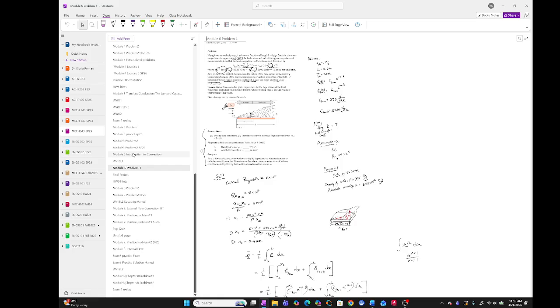Now, for intro to convection and external flow, I did go through the equation manual here in class. Everybody remember that? Boundary layer thickness, thermal boundary layer thickness, hydrodynamic boundary layer thickness, the Nusselt number. The Nusselt number, Prandtl number, Reynolds number relationship, for different conditions like constant surface temperature and constant heat flux. In external flow, what is the critical Reynolds number, all sorts of things, those are there. We explained all the equations. And the liquid metal is another important thing. In liquid metal it's usually laminar flow, but they have their own different equation. I showed it in the equation manual here in class.